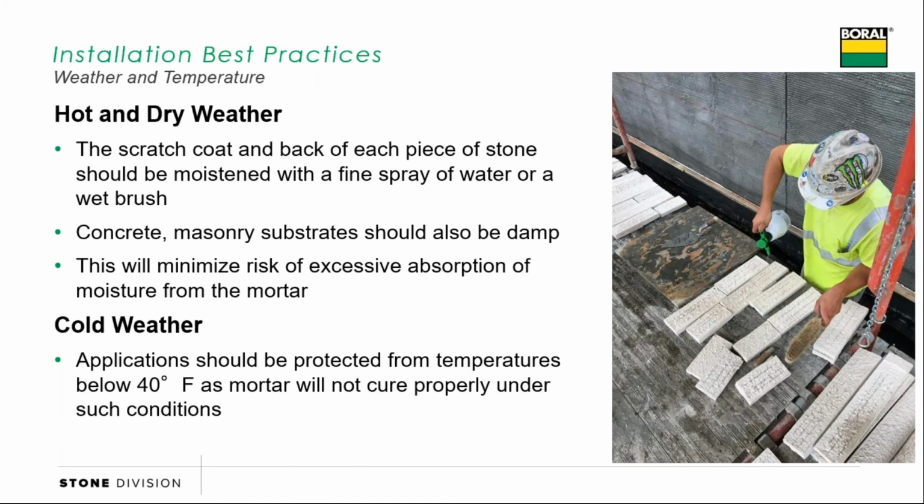The same thing goes for the bond. The slower it dries, the better it's going to be. Please don't install in cold weather, as we talked about. Make sure that mortar is protected until it completely cures.